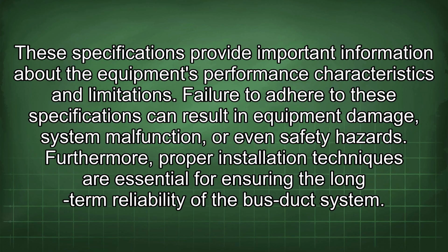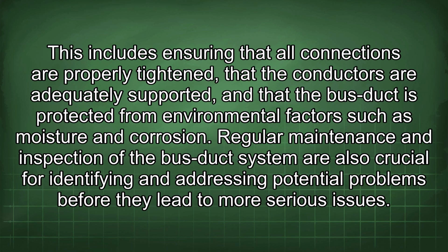Furthermore, proper installation techniques are essential for ensuring the long-term reliability of the bus duct system. This includes ensuring that all connections are properly tightened, that the conductors are adequately supported, and that the bus duct is protected from environmental factors such as moisture and corrosion.